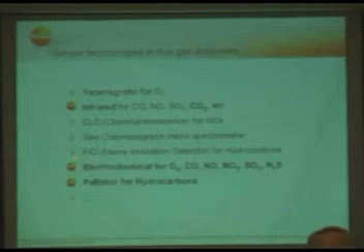We have FID technology for measuring hydrocarbons in the very low range, but these techniques, doesn't matter if it's CLD, gas chromatographs, or FID, are very expensive devices, and mostly they cannot be used in the field because of the rough conditions, like, they are sensitive against shock.